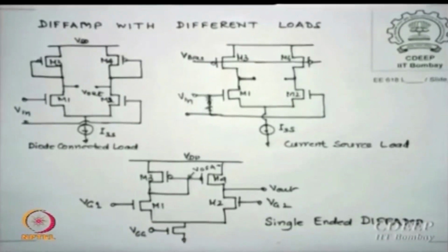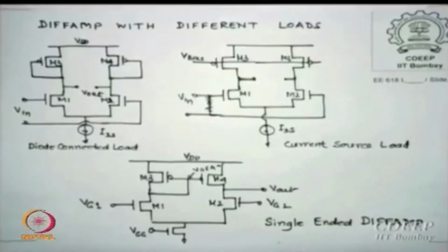This is what the single ended diffam essentially is, the most popular diffam, most popular simply because all first input stages of op amps are these, okay. But there, as I said the other day, there are fully differential diffams, or fully differential op amps, then you do not need both outputs, okay, fully differential, and at that time this cannot be used, either of them will be used in that. So inputs to outputs, is that called fully differential. So in those cases only you will require the first two, otherwise most general op amps' first stage is the simple single ended diffam.